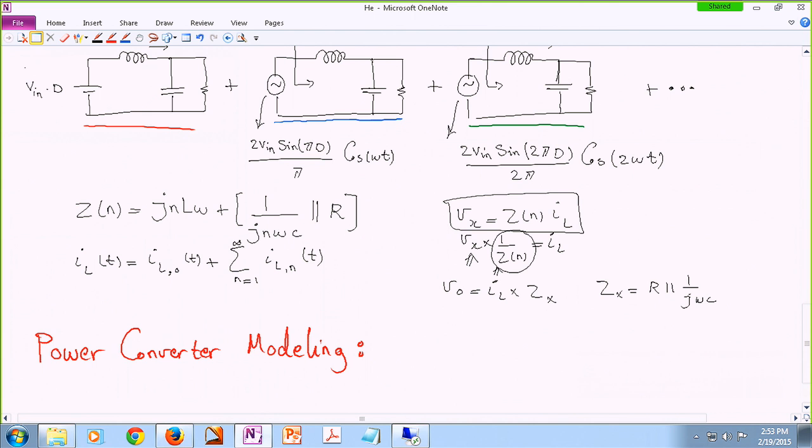For instance, you are running a very heavy simulation, you're using a lot of power, and then later on you pause it, and you don't consume a lot of power anymore. So the load, which is like that resistance connected to your buck converter, is highly unpredictable and variable. But the voltage that the CPU is being fed with is supposed to be absolutely constant.